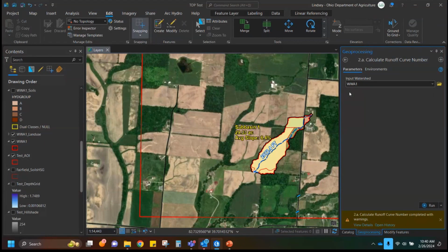Oh, Josh is raising his hand. You can unmute if you want to ask a question. I actually came across this last week on ArcGIS Pro, and it's just the merge tool. All you have to do is put the 2 soils layers in there and it will combine them together. Okay.